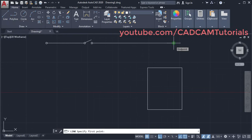Click on this endpoint. Take your cursor below. Now it is showing endpoint object snap. We don't want endpoint object snap. We want to create it straight. So what you can do is take your cursor to this endpoint, don't click there, and take it away. So it will track that point. Click there. Now our line is straight. Click, enter.